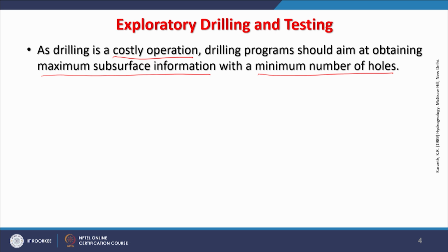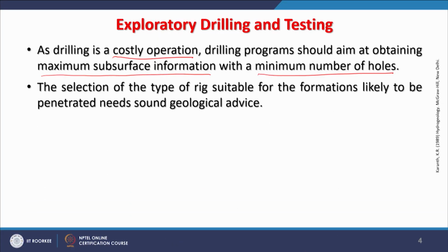Whatever material the drill is bringing up should be properly logged and kept, including what kind of small pieces of rock, or whether mud or water is being used. The speed at which the drill machine is going, everything has to be noted. That is what is meant here by maximum subsurface information.